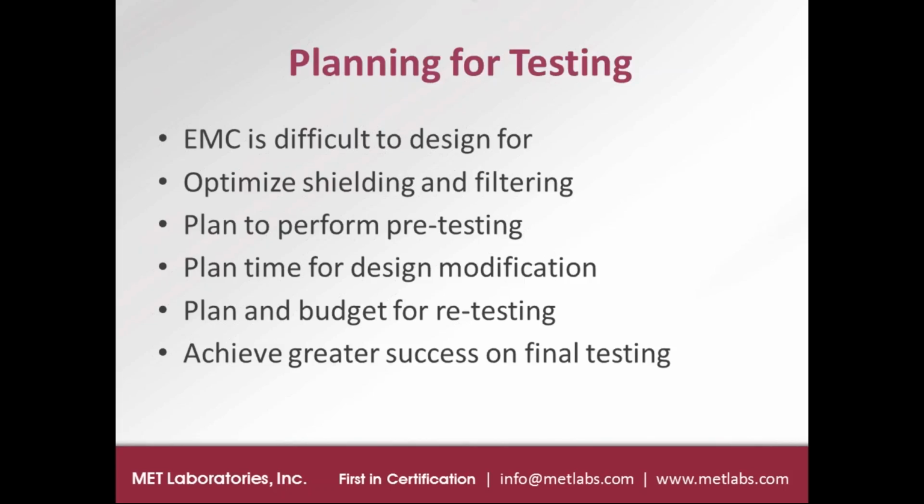However, if the design and the budget affords a shielded enclosure, a Faraday cage type design enclosure, then in most cases, it's required. If there's any electronic components in the device, you're going to need a Faraday cage design to enclose those in order to pass these requirements. And in a lot of cases, filtering will be required on the power input and also on the signal input lines in order to meet these testing requirements.